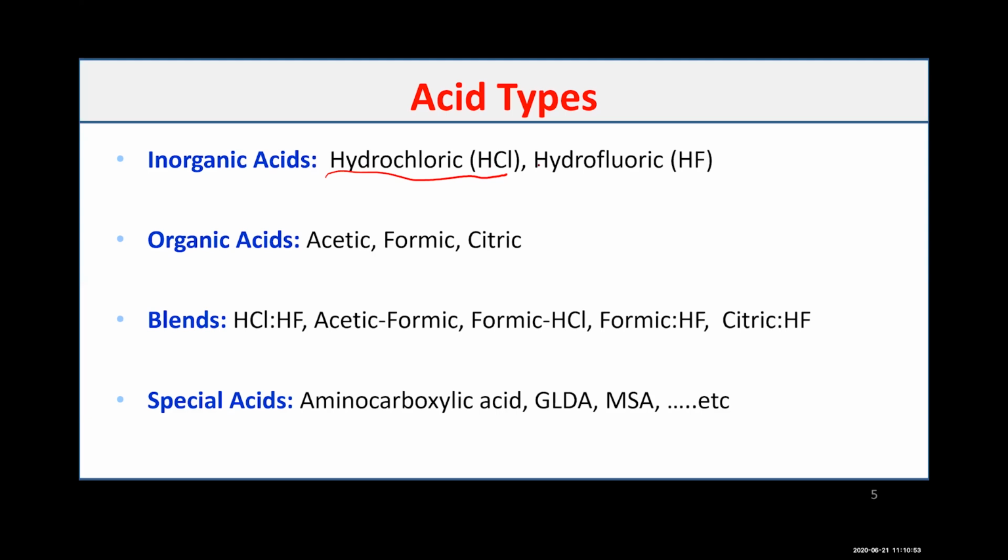The other inorganic acid is HF, or hydrofluoric acid, and this is the only acid that can dissolve sandstone, can dissolve silica. That's why when you hear sandstone acidizing, you should keep in mind that we are talking about hydrofluoric acid, as it's the only acid that can actually dissolve sandstone. None of the other acids in the industry can dissolve sandstone except HF. Therefore, any sandstone treatment must have a way to contain HF.